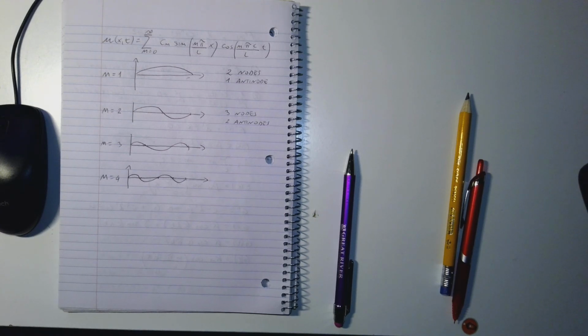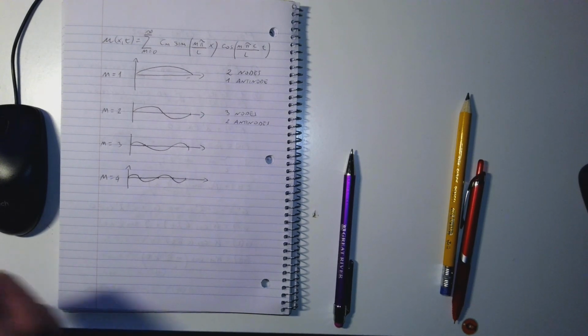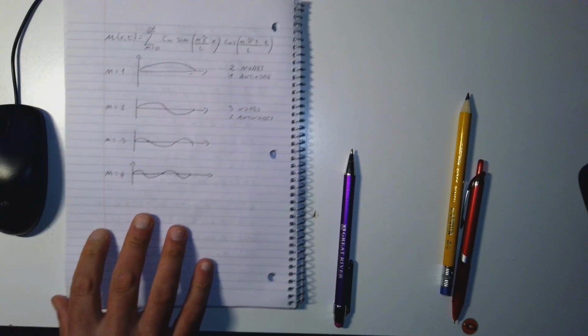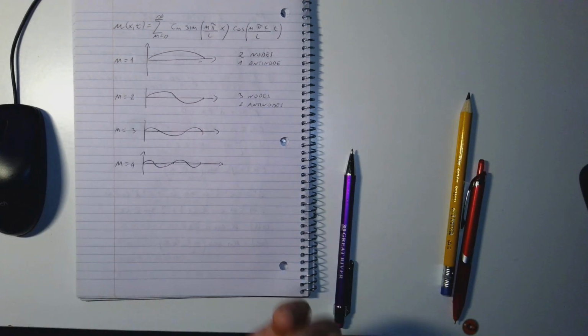Even in that case, depending on what type of external force you have and how it is applied, if you change the frequency of that external force, you may have a different amplitude of vibration. Typically, when you increase the frequency of excitation, the amplitude decreases. So you should look at the natural frequencies that come from all these modes of vibration.